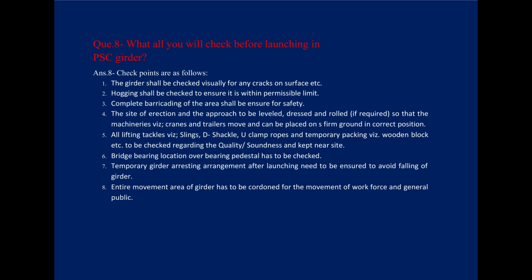4. The site of erection and the approach to be leveled, dressed and rolled, if required, so that the machineries, viz. cranes and trailers, can move and be placed on firm ground in correct position. 5. All lifting tackles, viz. slings, shackles, U-clamps, ropes and temporary packing with wooden blocks etc., to be checked regarding quality and soundness and kept near site.